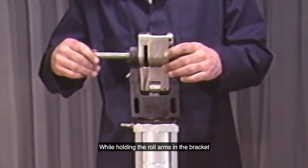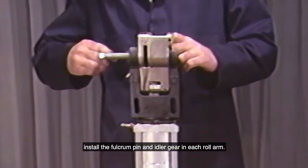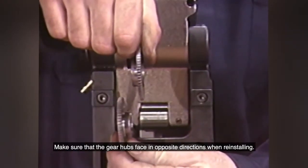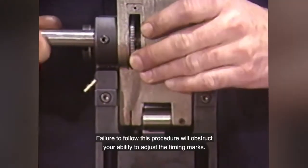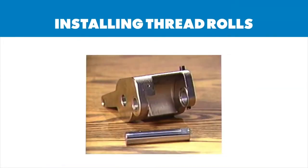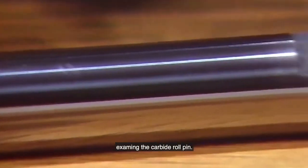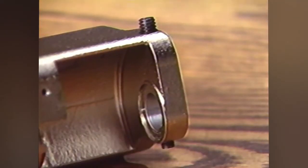While holding the roll arms in the bracket, install the fulcrum pin and idler gear in each roll arm. Make sure that the gear hubs face in opposite directions when reinstalling. Failure to follow this procedure will obstruct your ability to adjust the timing marks. Before installing the thread rolls, examine the carbide roll pin. Note that it's held in position between two set screws.